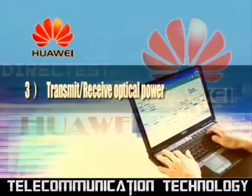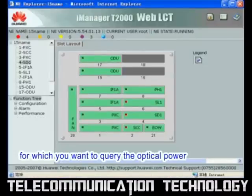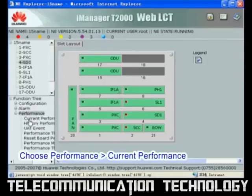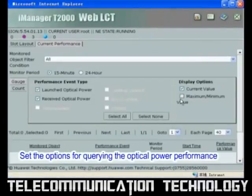3. Transmit, receive optical power. From the object tree, select the optical interface board for which you want to query the optical power. Choose Performance, Current Performance from the function tree. Set the options for querying the optical power performance.